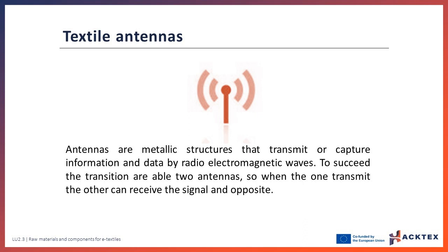In in-body communication, the antenna is in the body, and in off-body communication, a system provides a communication link between a wearable system and an external base station. The conductive elements can be made out of electroconductive textiles or can be screen printed onto the substrate material. The frequency that is used for the data transmission determines the shape and dimensions of the antenna, so the smaller the operating frequency, the larger the antenna patch will be.